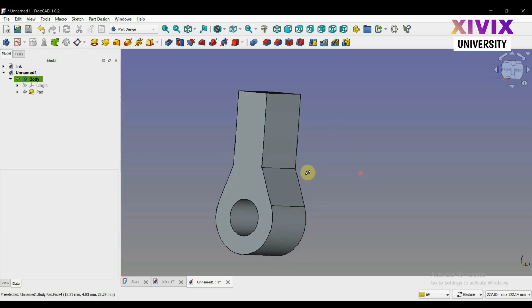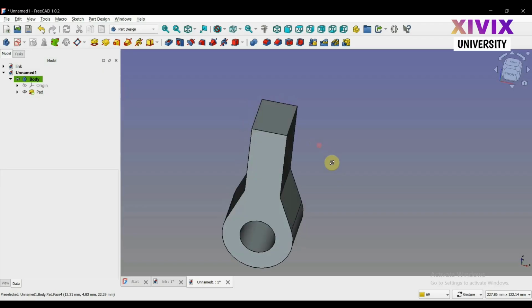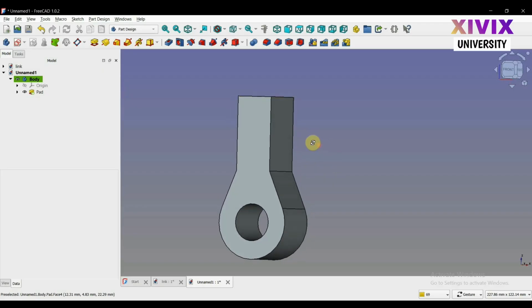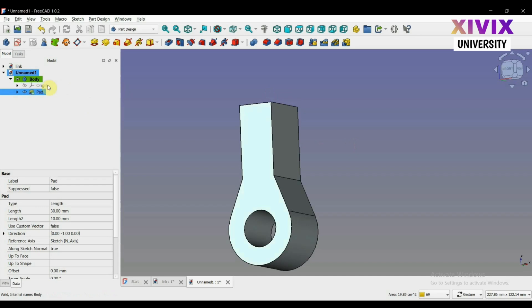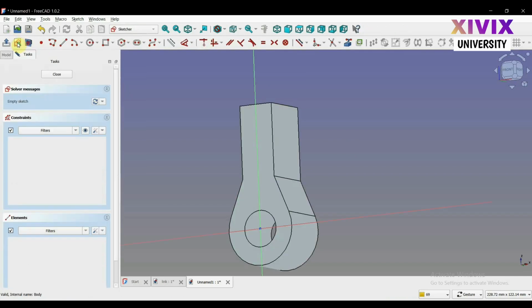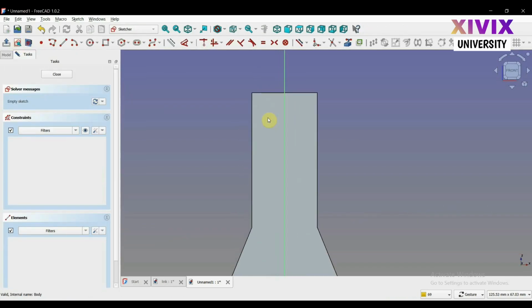And now we have to cut another set of circles, so I'm gonna choose this surface and create a new sketch. And this is the external geometry. What it actually does is that it lets you connect your sketch to an existing sketch. Pretty much like the shared geometry from another sketch. So click on this and apply it onto this line.